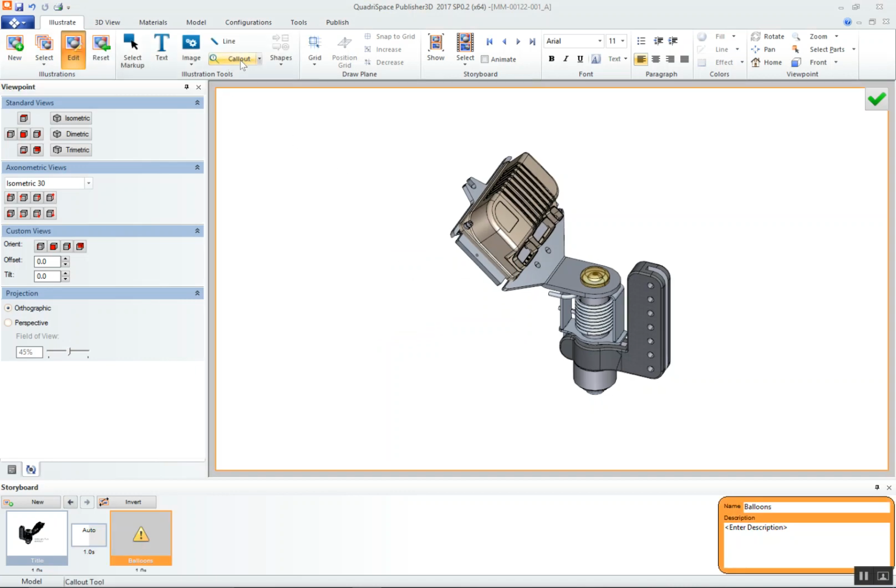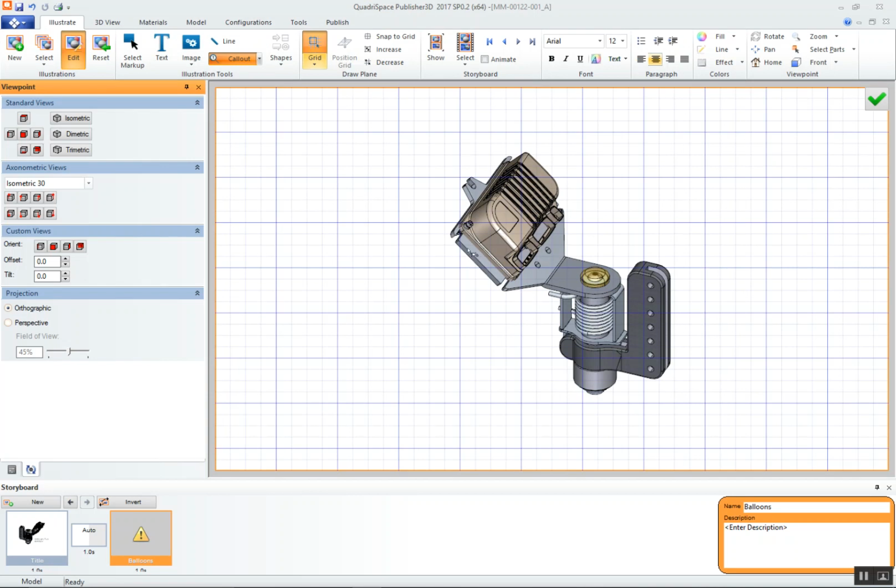You use the callout tool, and you can click this, and then you just begin to drag off from that point. Well, I picked the same part twice, so I'm just going to delete that one. And this is how you can do it manually. In a moment, we'll talk about how you can do a little more automated version of pulling off of these balloons. So let's see. Grab a few more here. We'll call it a wrap. Okay.